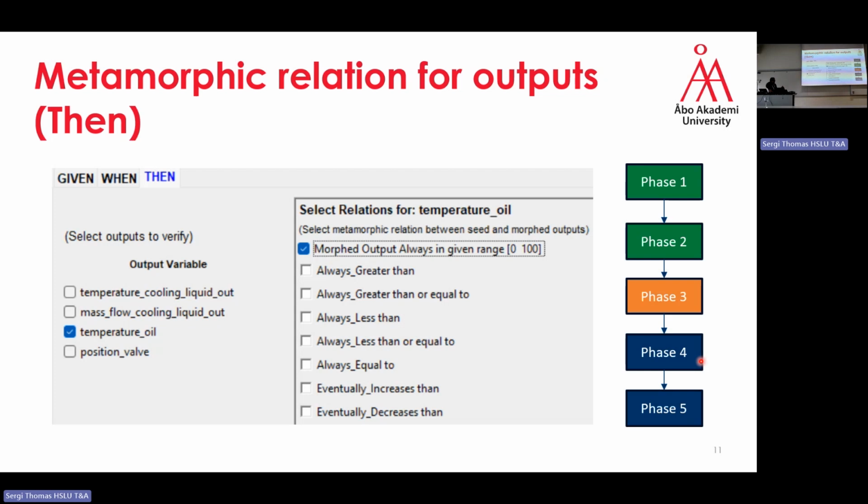And usually what happens in this testing is, even though the temperature has a defined range, for example 65 and 80, usually when the FMU is verified, the simulation is run once with an average temperature of this value range. So metamorphic testing allows us to define structured test input patterns, which can be used for checking the correctness of the system, its logical consistency, and whether it is behaving as expected.